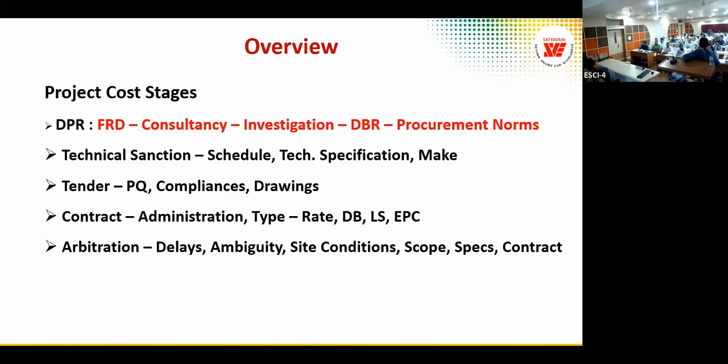Actually, many people think, in fact, I have seen tenders for DPR that mention you have to give the construction management method and the contractor pre-qualification. All that should be mentioned in the DPR itself, because they all affect cost. The contractor, the technology adopted for construction and the equipment used will determine the number of labor required for the project.